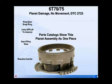So what we're telling you to make sure you do is understand that you have to order both the ring gear and the Planetary as separate pieces. They don't service this as one piece. This is snap ringed in position here. So the snap ring's on the inside diameter of the ring gear teeth. So bottom line is, this can be a self-inflicted wound, cost you a lot of hate and discontent, because you're going to take the transmission back apart for this issue. So make sure we get all the pieces in the transmission.